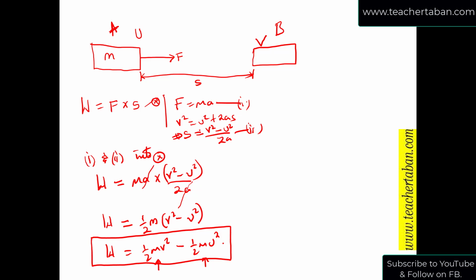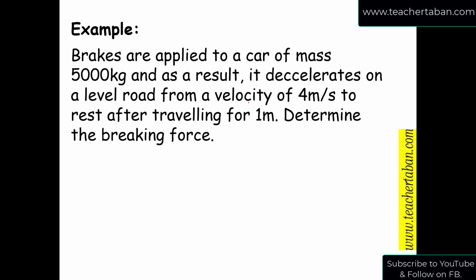Let's have an example here. The question says that brakes are applied to a car of mass 5,000 kilograms, and as a result it decelerates on a level road from a velocity of 4 meters per second to rest after traveling for 1 meter. Determine the braking force. When answering this question, the first thing to do is always to summarize what has been given to you.